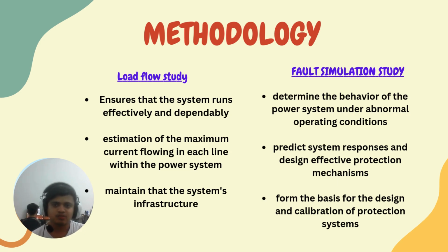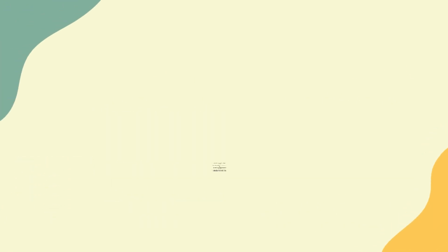Worst case scenarios can be simulated to find which points of the network are most vulnerable, on which basis discipline can be developed by the engineers. It will also serve as a testing ground for the protection scheme to be applied on the system for its accuracy and reliability. The results of this step are of prime importance in setting the overcurrent relay and in making the system operate within the realm of safety under variable fault conditions. Generally, a fault simulation study can be regarded as a fundamental part of protection design in our systems and contributes to its stability, reliability, and overall performance.